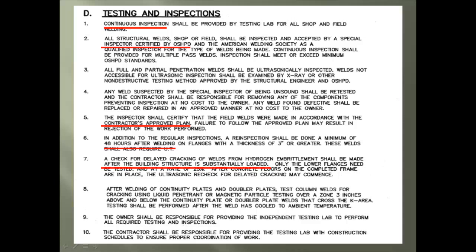Here, an alert for all personnel. It's a check for delayed cracking after the structure has been loaded with concrete. The owner will provide the third-party independent testing lab. And it's the contractor's responsibility to provide the testing lab a schedule for proper work coordination.